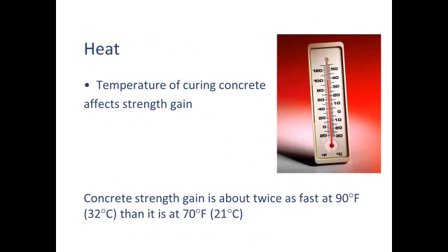So I had mentioned that I was going to talk about a different kind of accelerator other than chemical. And the most common, perhaps the oldest, is heat. Commercial precast, they use steam curing. When you warm up concrete, and it's not just the surface, but you're warming the full body of the concrete, the reaction rates speed up.